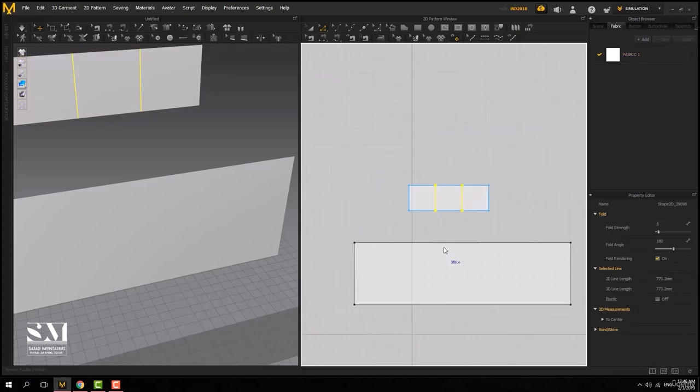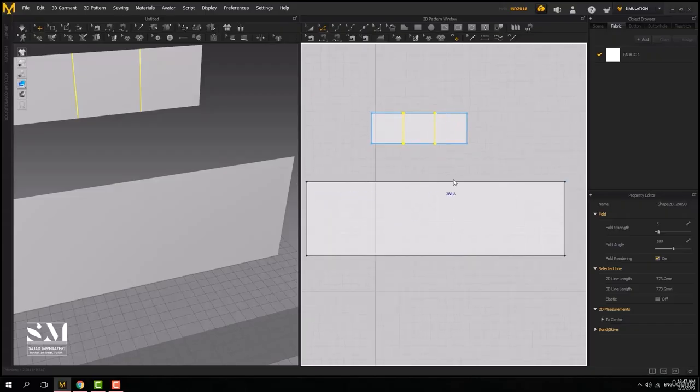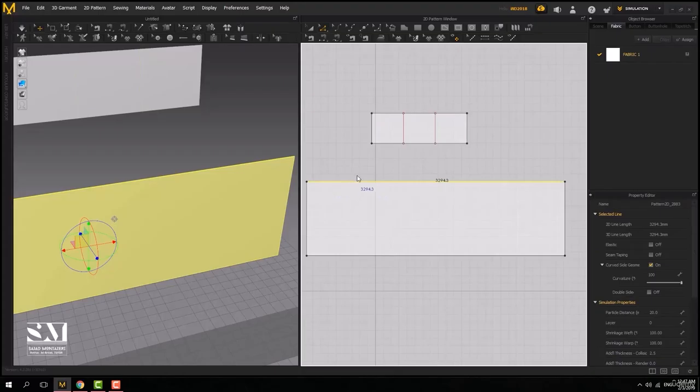here. In the previous exercise, if you remember, we copied 3 of these, then merged their boundaries. And this time I don't want to do that. I want everything done on a single separate rectangle. Look, I've set the count to 3. The number of splits on the bottom must be a multiple of 3. For example, 3 times 3 or 4 times 3 equals 12 can fit.